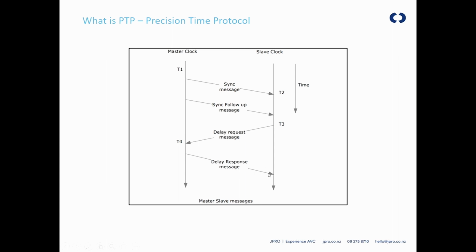And then only on the last point does it receive this. These physically appear as packets on the network, so you actually do see these transmits. If you were to Wireshark a PTP protocol, you will see the sync, follow-up, delay request, and delay responses around that. What we understand at this point is that we're currently referring to switches, but these can also be devices. So if my Dante master clock sends out a PTP clock and it's received on my Dante IO unit, the slave unit, then it's using the same methodology to work out what the sync is for the network.